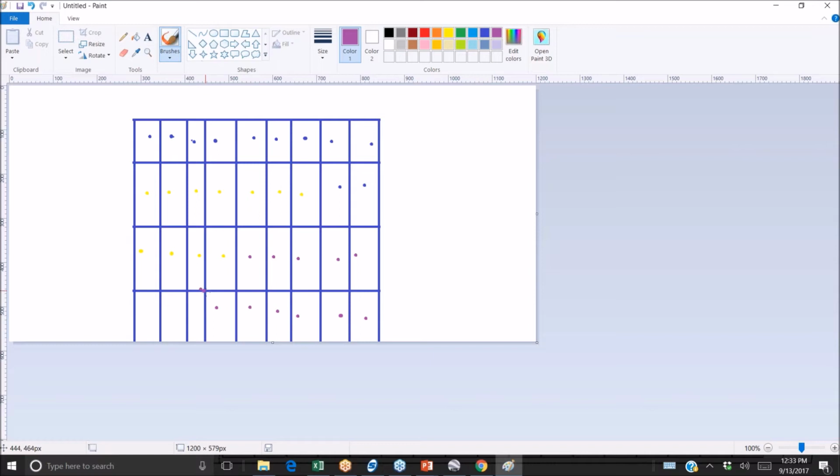And then these three modules, I might go back and say, okay, actually, I have 3 more modules and I have 3 circuits. So if I'm allowed to do 3 circuits of 12, I make that circuit 12, and then I have this circuit, and that's 1, 2 extra. And now with 12 modules per circuit, it's all nice and neat and organized.